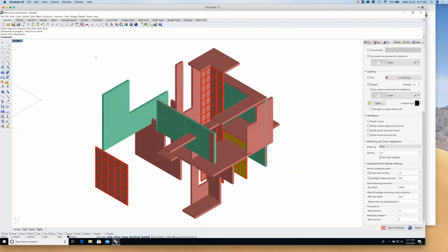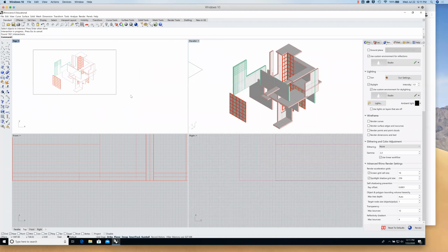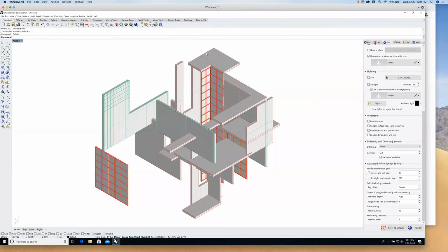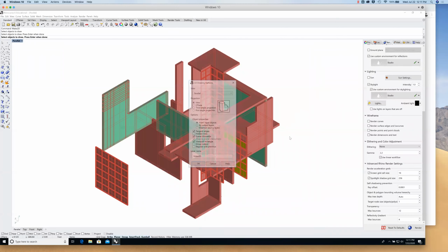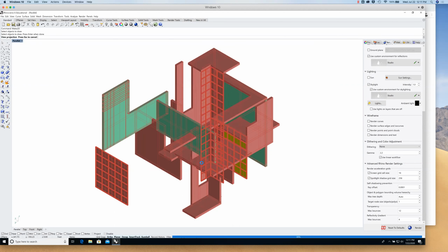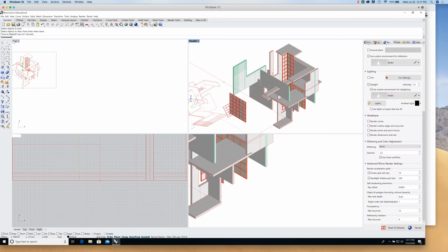So, all right, now I'm going to redo the Make 2D, okay? Let me go back to my top view. I'm just going to go ahead and select this old Make 2D drawing and delete it. Go back to Parallel and Make 2D. Run that command again, select everything, hit enter when I'm done. Double check my properties, tangent, scene, silhouette, viewport rectangle, okay. Watch it work. Now I'm gonna go back to top view.